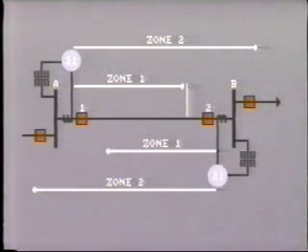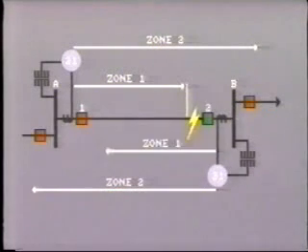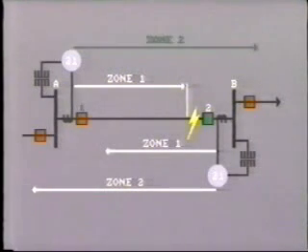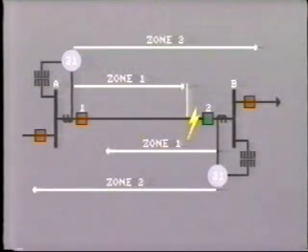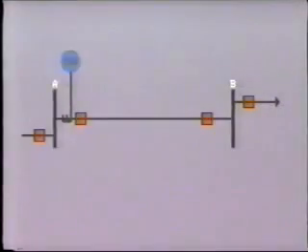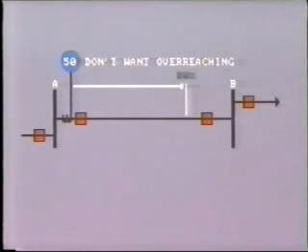Even with distance relays at both ends of the line, the problem persists. In this instance, breaker 2 trips at high speed on the zone 1 element of the number 2 distance relay, but the clearing of breaker number 1 still has to wait until the zone 2 element at this bus has timed out. With instantaneous overcurrent relays, we have another problem. Due to their lack of high precision, the instantaneous relay is set to cover only 80% of the line. This is necessary to prevent the relay overreaching into the next section of line.